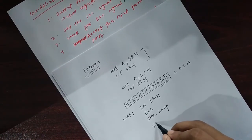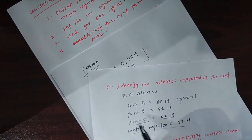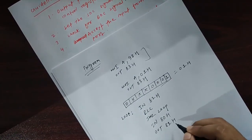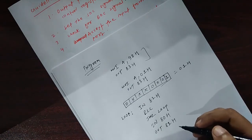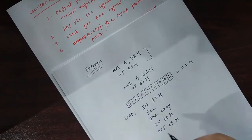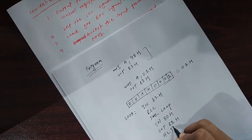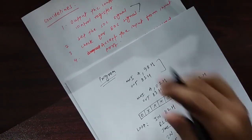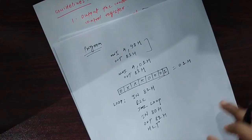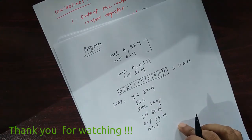So IN 80H, which is the address of port A, and then OUT 81H, because we need to output the inputs from port B. So port B has address 81H, therefore OUT 81H, and then HLT, to stop the program as stated in guidelines. Okay, so this is the program, and we are done with all of the questions asked in this problem.